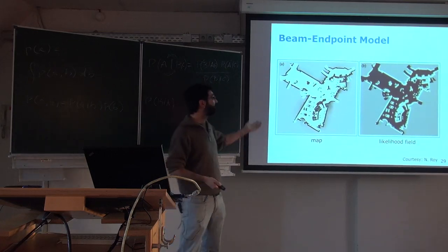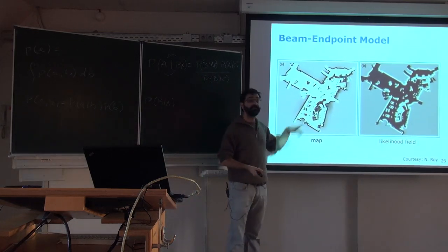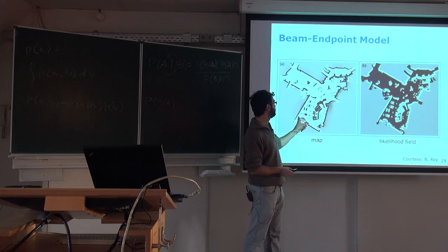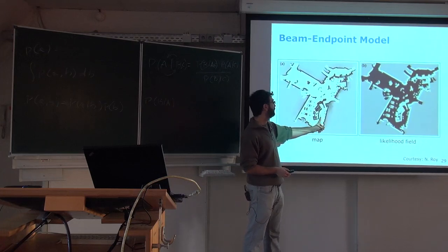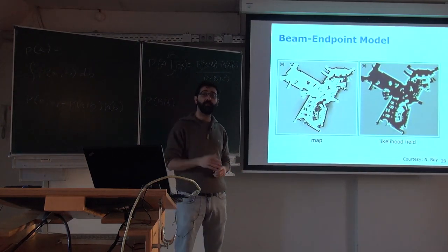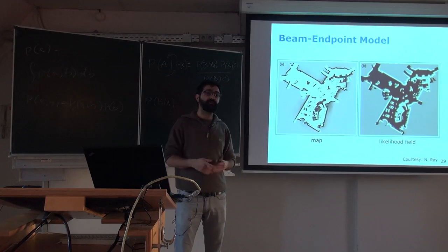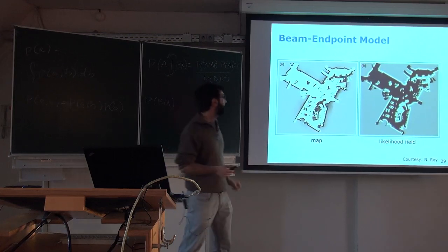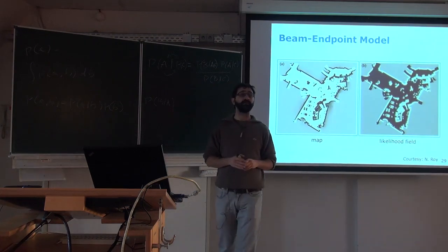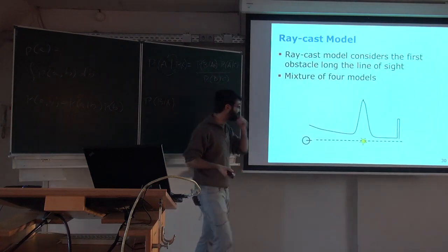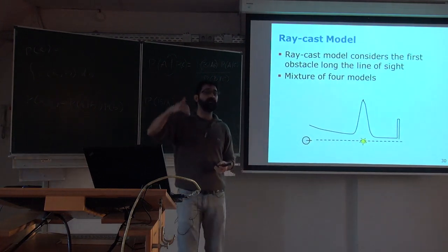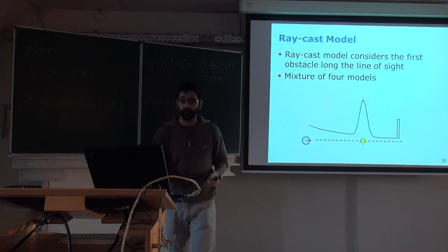One pitfall of this is that you do not consider the free space at all. So it might be that the robot is somewhere here and there's an observation there, and you don't consider the fact that it's actually looking through walls, okay, which can be a problem because it will give you a likelihood value which is not exactly what you would expect, no? But in case the robot is well localized, this is actually not a big problem. A different way of also considering free space is what's called the raycast model or the beam model. So not the beam endpoint, but just the beam model, where what we...